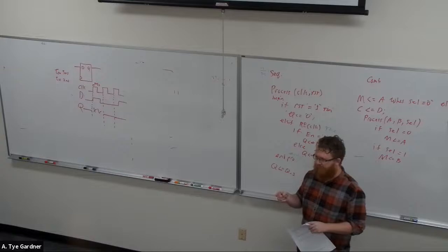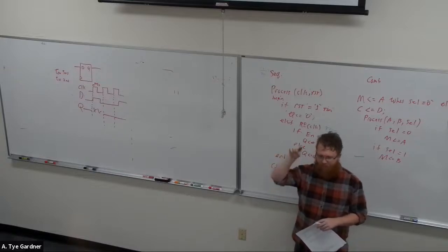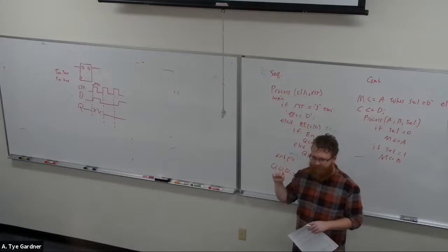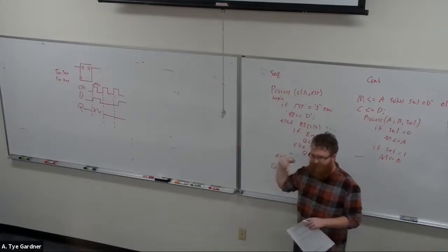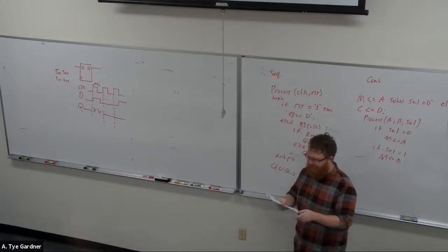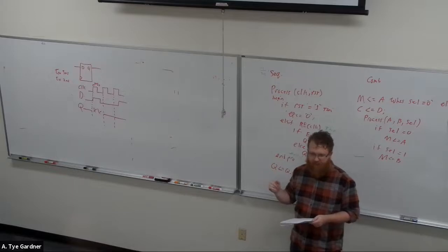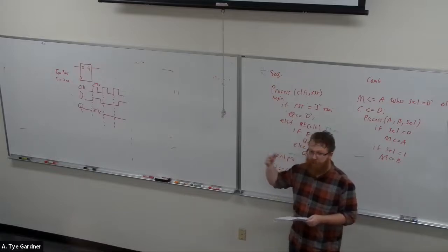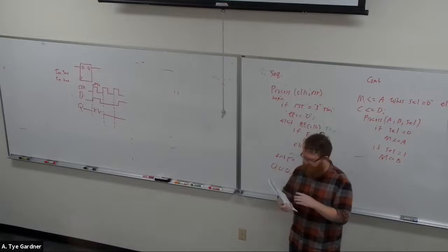So we talked about the ripple carry adder, which is just stringing full adders together. Then we have the fast carry adder, where we built the AND and NOR gate network in order to calculate the carries ahead of time, right, in order to make it faster. And so this has some questions around the propagate and generate functions that we talked about, right? Either it can propagate a one through or it can generate a carry on its own. And you might just have to answer some conceptual questions about this one. I'm not going to do the questions that they have on here. It's a little bit more